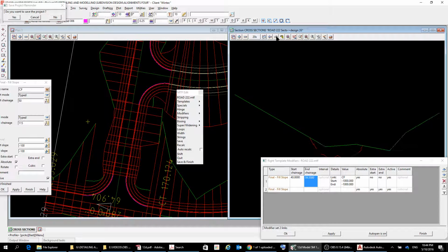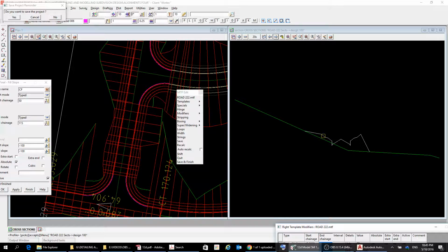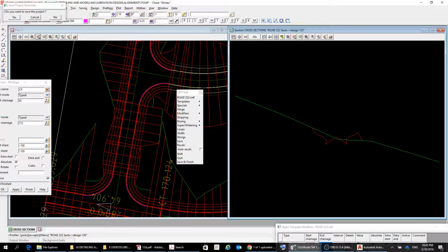There's a little bit of downslope over there, but it is sloping in the other direction, which is good. And then as we come up to here, if we just grab this out of the way, we can see that although things are sloping down, they're sloping down and continuing down. So the fill there, the water is draining, well, it's not draining to the road, it's draining away from the road.